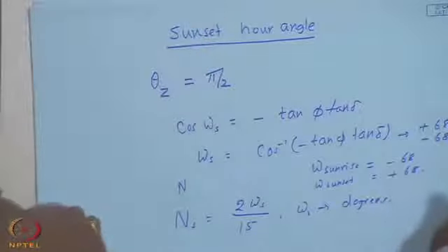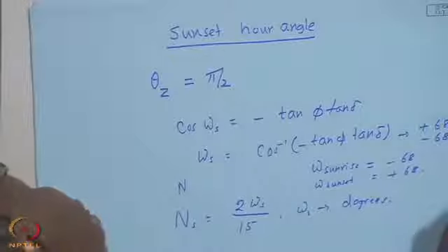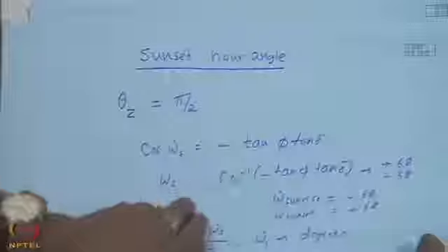You have to be careful whenever we are using trigonometric relations, whether degrees or radians. As a process of integration, if you get an omega, that has to be always in radians, whereas sin 30 or sin pi by 6 is one and the same thing. Whereas, if I multiply by omega s, this omega which resulted from some process of integration or differentiation, I have to use only in radians. That you have to remember. Now, this equation gives some problems.